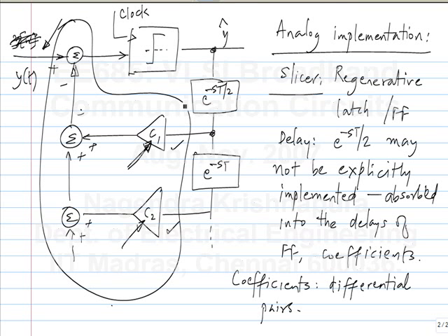So the delay through this can be the symbol period T plus or minus some value. It's not necessary to have it exactly at T. If it varies a little bit, it changes the shape of the eye diagram, but it may not change the values at the sampling instant too much. What will happen is horizontally the eye will become closed a little more. So some variation is tolerable, and typically you find that using simulations.